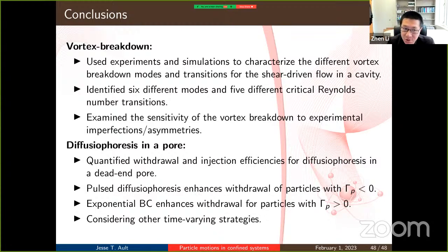I'm not sure if you add something, for example a polymer solution, where you can change the viscosity but also add a little bit of viscoelastic property to the phenomenon, whether this will give you a consistent observation, or whether introducing viscoelasticity will change the phenomenon when you only use the Reynolds number to quantify it.